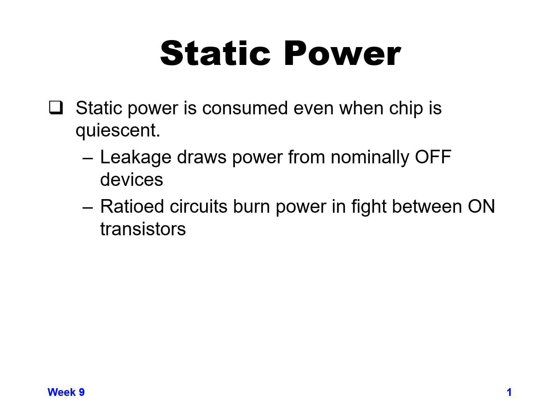In other words, when the chip is not actively toggling any internal nodes. So you still have a power supply going to your logic, but it's just holding the values that it previously had, all staying in a static state. Everything that was a 1 previously stays a 1, everything that was a 0 stays a 0.